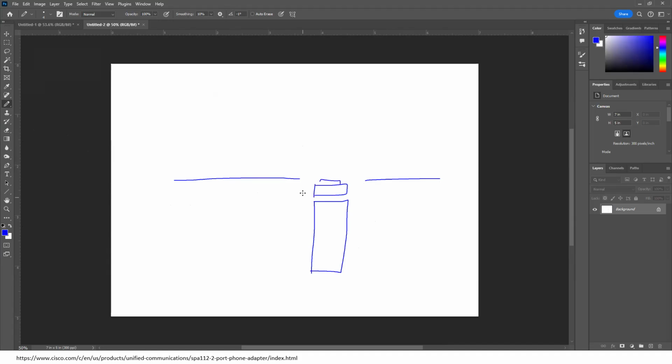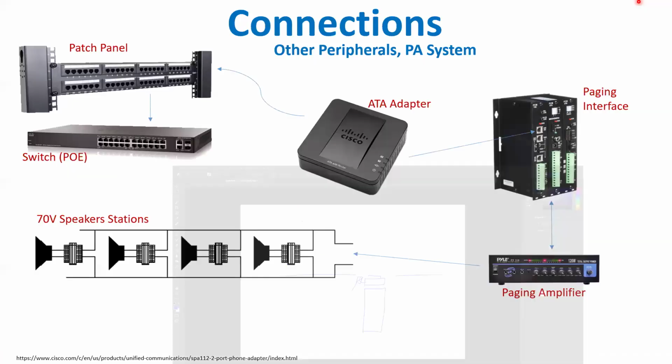Okay. Now on the stick right here is going to be something that's called a door station with the push button. So the truck driver just pushes the button here, and it's a hot dialer that dials whatever extension is programmed to. So that hot dialer, or the door station, or the truck driver station, whatever, the push button station, it is connected to the ATA adapter.